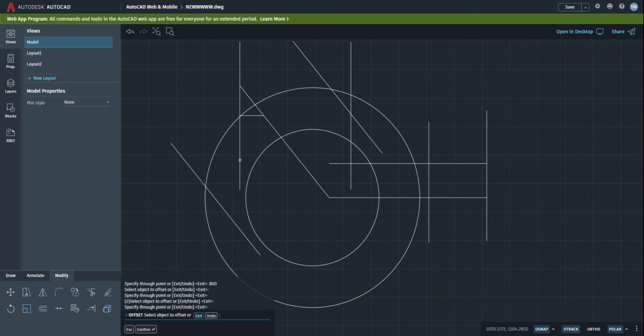You can do an awful lot in AutoCAD just by using those five commands: circle, line, offset, trim, and extend. Have a play, get used to using them, and I will put up another video that walks us through doing a simple engineering drawing, just so that you can see how I do it and maybe start to copy that workflow.